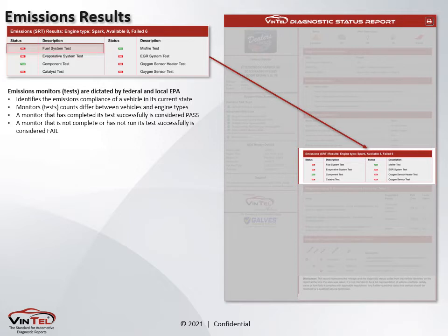In this particular emissions monitor, we're looking at the fuel system test, which for this OEM is a continuous monitor. And since this continuous monitor on this drive cycle has failed, it now shows the failure mark in the status.